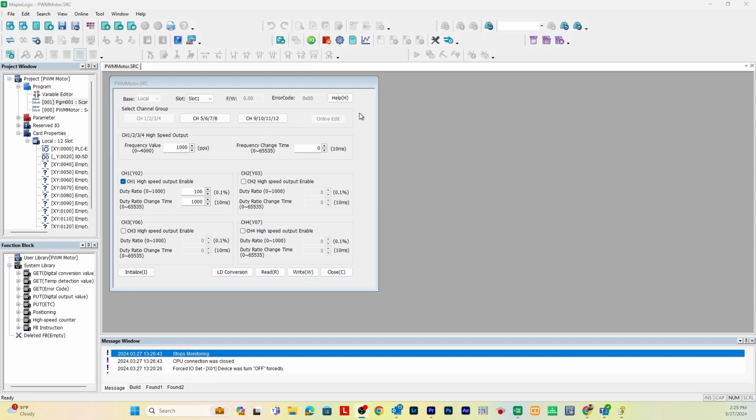So this PWM configuration window can effectively change the duty cycle and frequency, for example, of an LED light or a motor. It can change the brightness of the LED light from dim to its brightest. So at a low duty cycle, it would be dim, and then at a higher duty cycle, it would be bright. Or it can also affect the flickering of an LED light, or just pulsing on and off, depending on what kind of LED light you have.